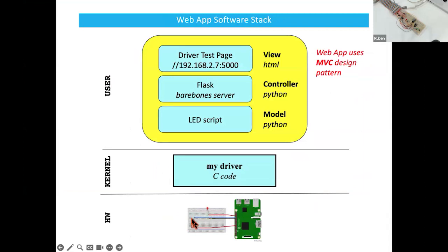You've got an interrupt button down there, which can turn the LED, which can access the GPIO registers, and also this user process can access the GPIO registers. You've got two things going on that can access the registers at the same time. So in your driver code, you have to make sure that that doesn't cause any corruption of the registers when you've got something like that going on.